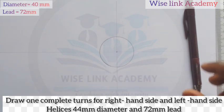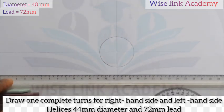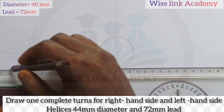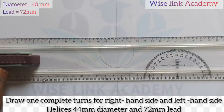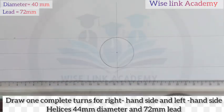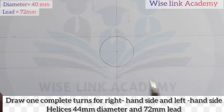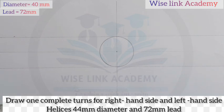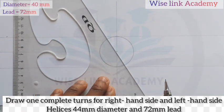Having considered this, my next task is to take my T-square at the bottom of the circle, the circumference, and draw a horizontal line this way. Similarly, take it up this way, and do the same procedure. Now, my next task is to divide this circle into 12 equal parts. How do I go about that? Simply take your 60-degree set square this way.